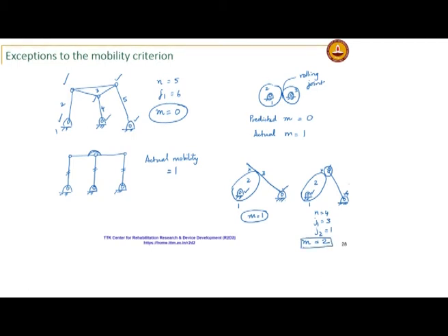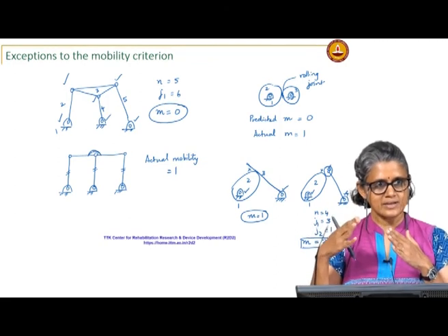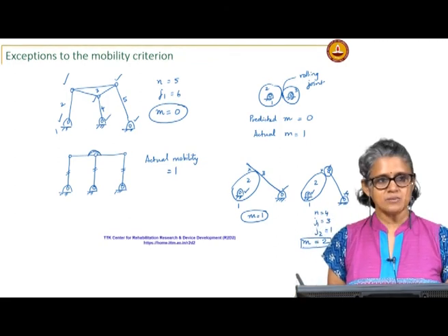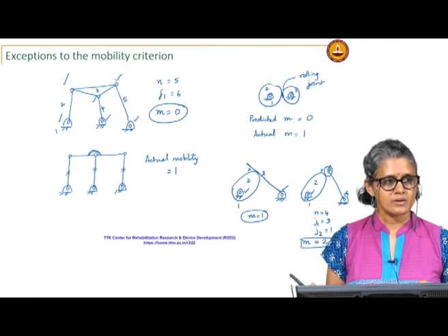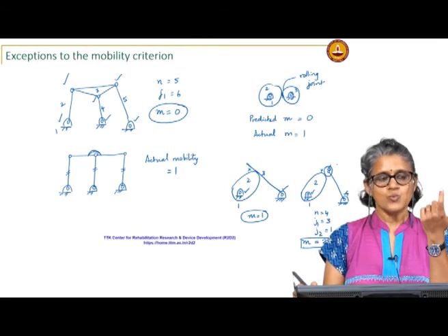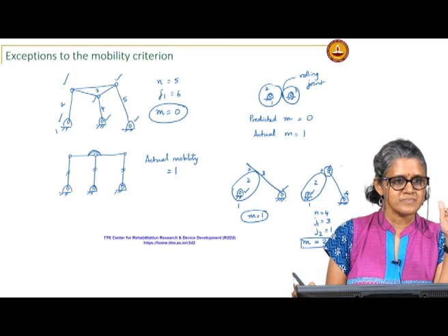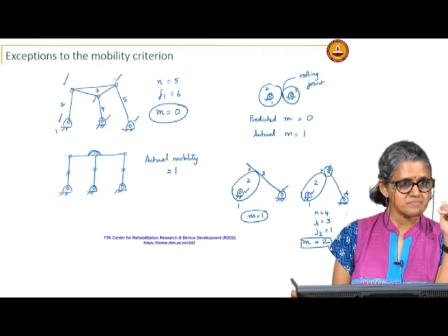It is pretty much the same. If you look at the input and output, you will get the same result in the output. So, if I move this cam, I get a predictable motion of the output link here. So, what is this additional mobility that we have here? It is the angle of the roller about that, which for your practical application does not matter, but it is an existing degree of freedom in the mechanism.